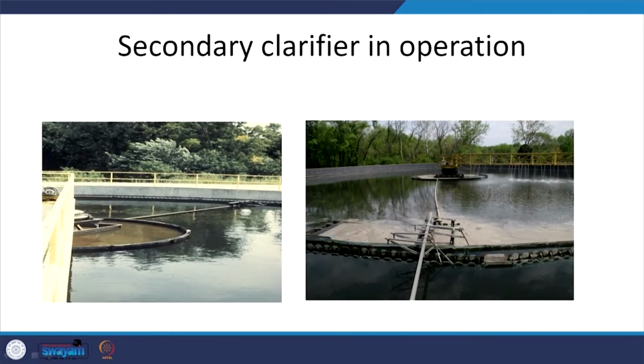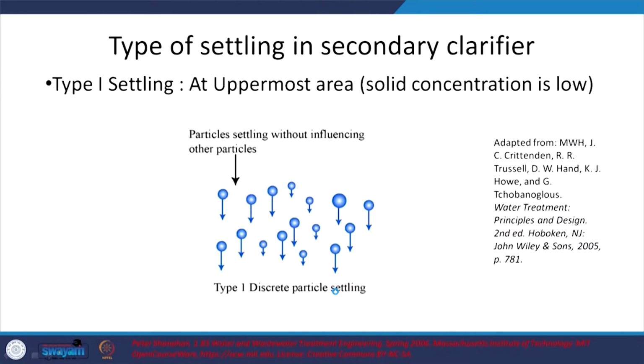So, you can see in the internal basin the quality of the water, and by the time it goes out here, this is where your effluent will be, the treated effluent, and that is where you see it is relatively better. And depending upon the maintenance of such, you can have scum or even sometimes nocardia foaming, but foaming typically in the aeration tank, not here. You can see this scum being removed by this scum scraper. So, you see the baffles and then the treated water, this is the treated water here, right. So, let us see what else we have.